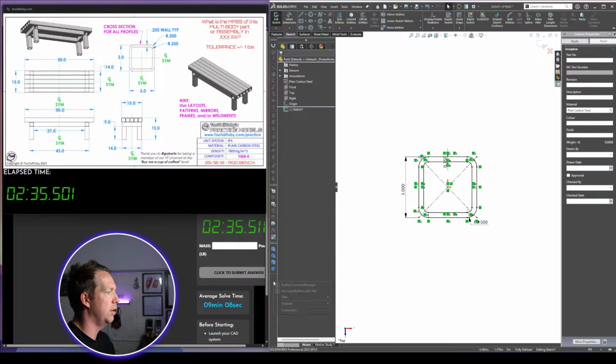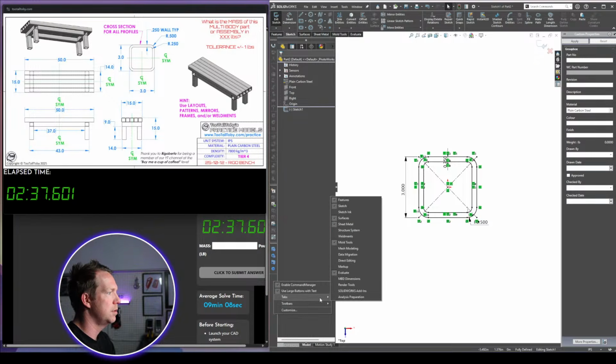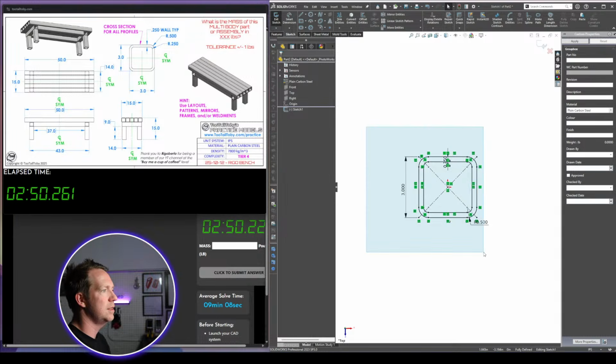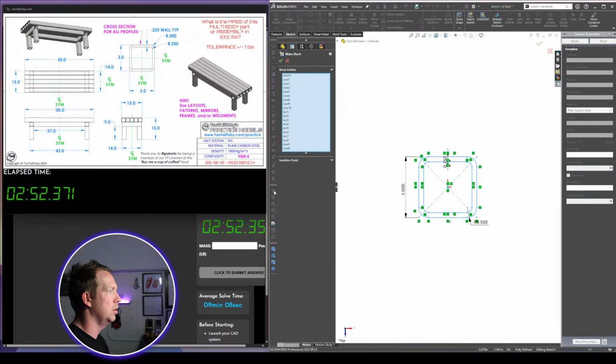Now I've used that by right click, tabs, toolbars and blocks. So blocks are essentially groups of sketches in SolidWorks, like you would group something in Illustrator or AutoCAD, etc. Now when I select it all and press block and save, it's going to include all these entities.